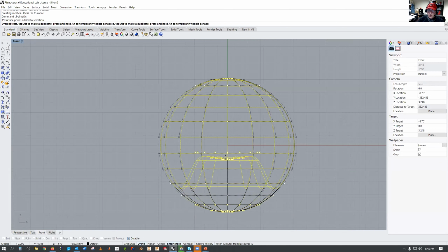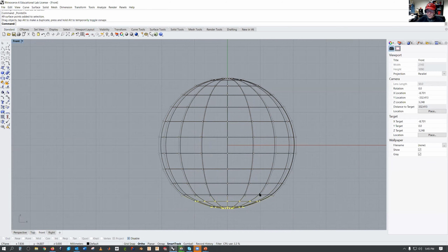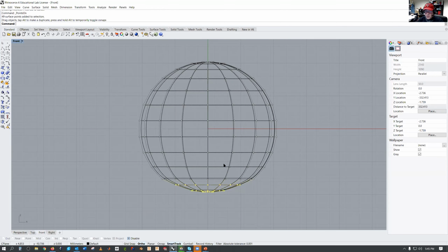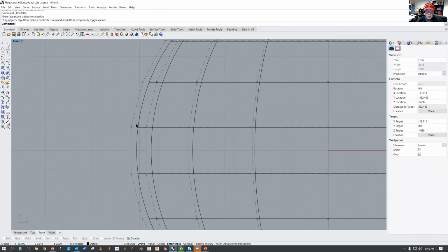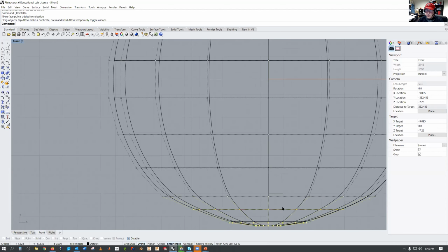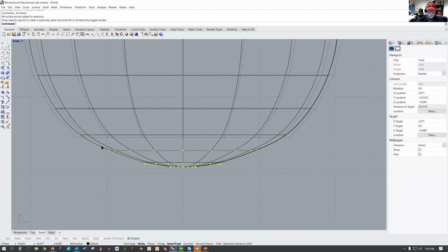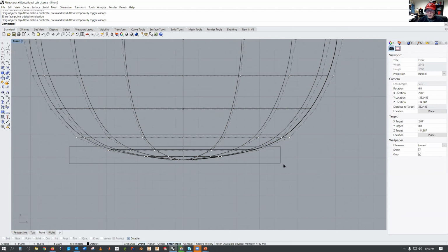And I'm going to make sure ortho's on, so it only goes in one direction. When you're playing with these control points, you can really deform the shapes and cause errors, basically. As you saw with the spline in the PowerPoint, these lines are going to be outside your surface, right? So they're going to be guidelines for where the object actually is. And everything's going to wind up being approximations because this is all a perfect sphere, right? So no such thing.